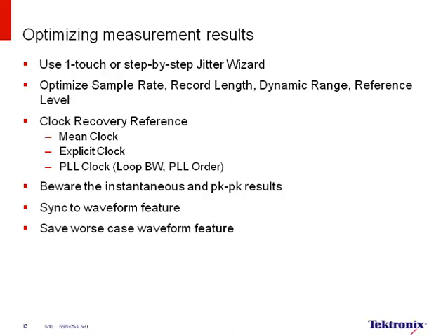There are other techniques, for example, to help you improve your jitter analysis debug. So, for example, there are ways for you to sync to the waveform. If you have a specific TIE or cycle measurement that has a high value, there are ways to go from these views directly to the waveform view to correlate why you might see a high TIE. And you will see in most cases that the correlation will show up at the end of a long run length, long ones or zeros. You'll see this high jitter.